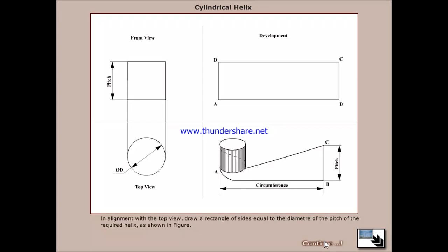Let us observe the development of the front view. Now divide the circle into 12 equal parts and name the division points as 1, 2, 3, etc. in the counterclockwise direction.